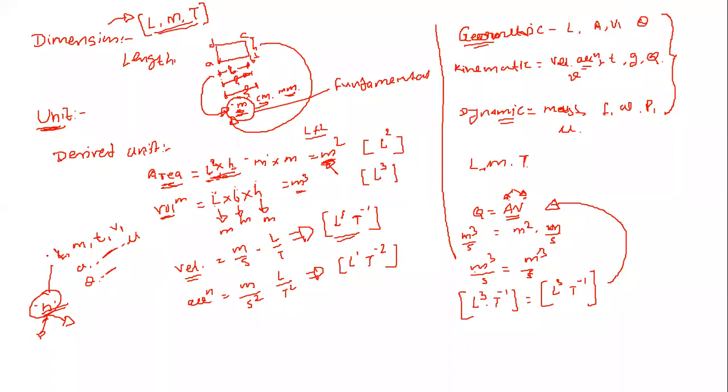Parameters are involved. Those parameters were considered as n number of parameters. From all those n parameters, after putting their dimensions, that is, by putting the dimensions of length, mass, time, temperature, velocity, acceleration, those are involved in this particular phenomenon. If we are getting m number of physical or fundamental dimensions, say three fundamental dimensions, that is L, M, T. Means out of these n variables, if those n variables contain the m fundamental dimensions, then we can group